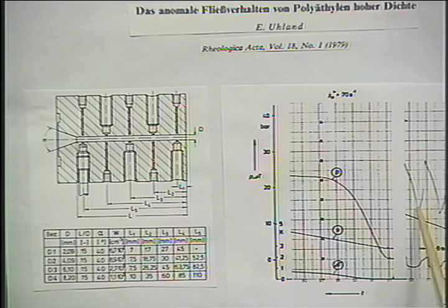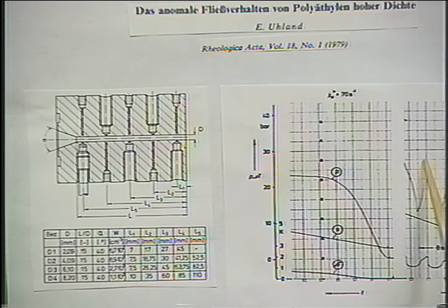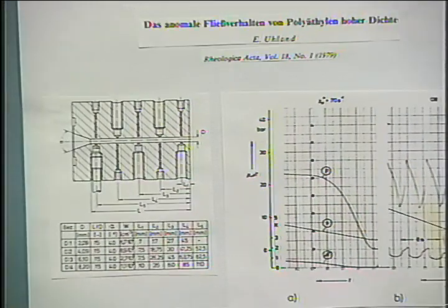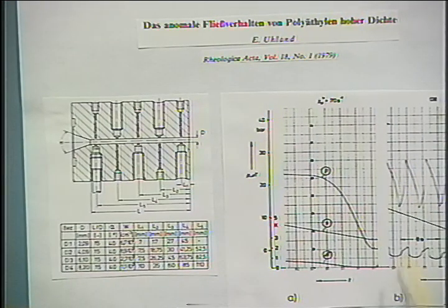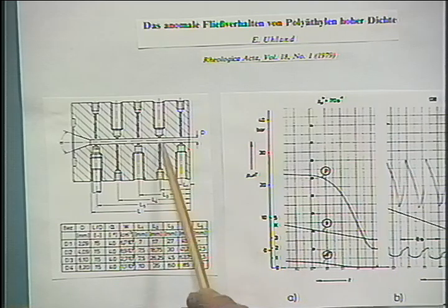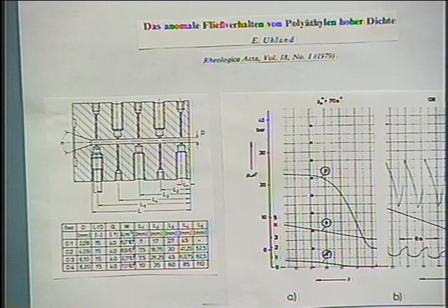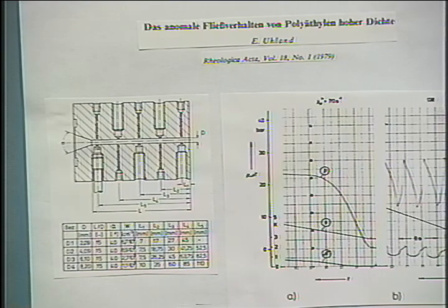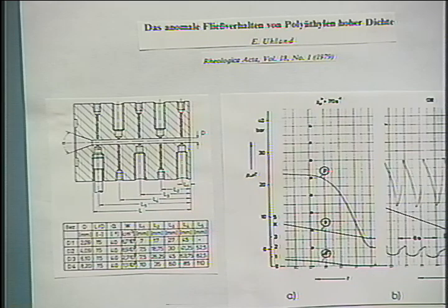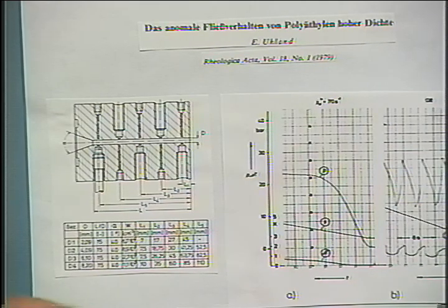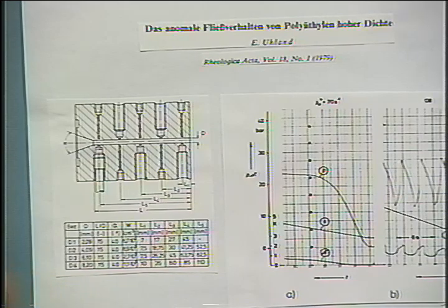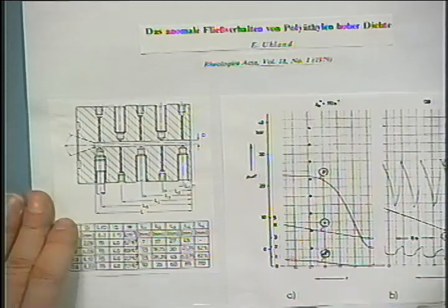You can see that when the pressure goes up very high, it builds up during a sticking operation, and then there's a rapid discharge of this capillary rheometer, and the pressure goes down, and at the same time here you see viscous dissipation, you see heating effects on those thermocouples. Always when you have slipping, you see all the energy which is used for pushing the polymer through the capillary is converted into thermal energy, and you can pick that up with a thermal sensor near the wall, and then the thermal sensor goes up and down the same way as the extrudate.